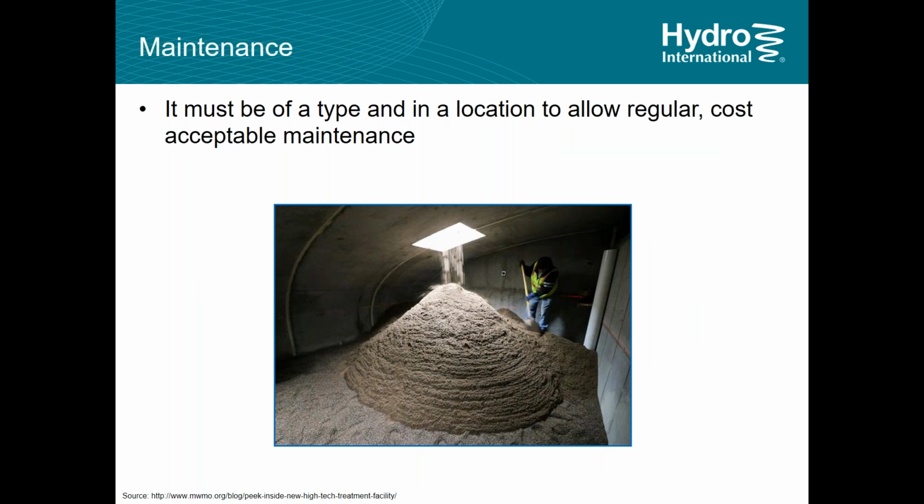And one really important aspect, this is where the stormwater treatment industry in general is just starting to get its brain around, and that is maintenance. You've got to design these for maintenance. You've got to design any stormwater BMP so that it can be maintained.